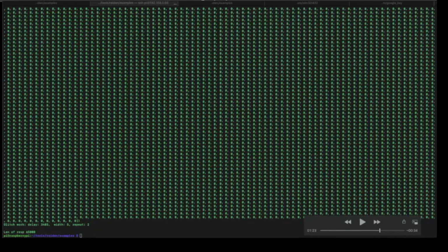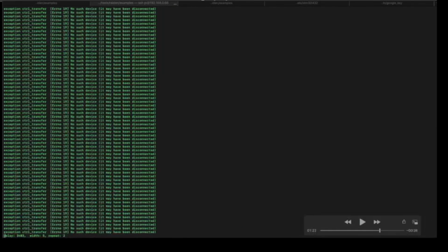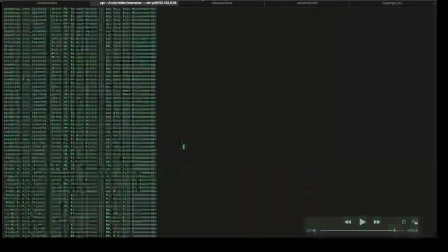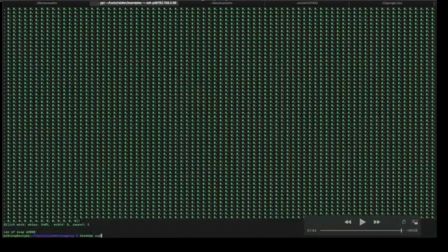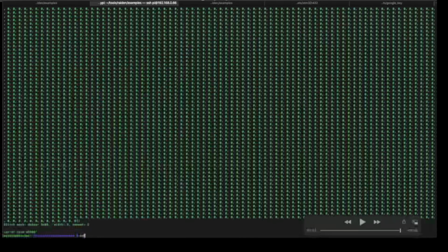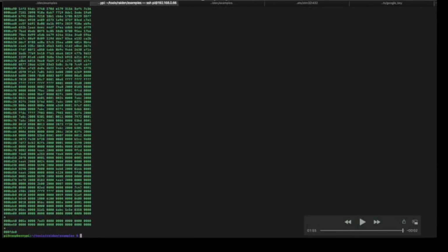IO under the min function that we configured, and here we get like 65,000 bytes of data. If we do a quick hex dump of the information we just received, we can see a bunch of good bytes, which means we corrupted the min function, and we actually received more data over USB than we expected.